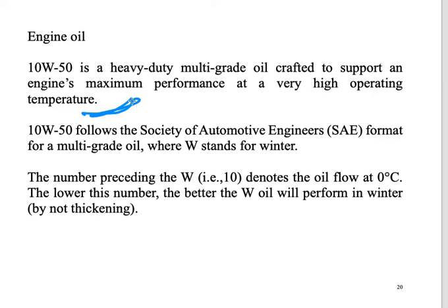in a certain range. Because previously in our class here, we found that, even for the viscosity of water, normally the viscosity of oil will become lesser and lesser at high temperature. So if the engine oil is very thin, it cannot lubricate the contact surface very well, so it will lead to engine failure.